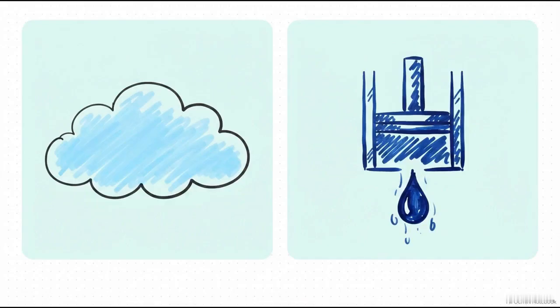Before compression, let's take 8 cubic meters of air. At 20 degrees and 50% humidity, that air is naturally holding 8.5 grams of water per cubic meter. Now the compressor kicks in. It takes those 8 cubic meters and violently squashes them down into just 1 cubic meter. Now, all that water vapor didn't magically disappear, right? We just forced 8 cubic meters worth of water, which is 68 grams total, into a tiny 1 cubic meter space.